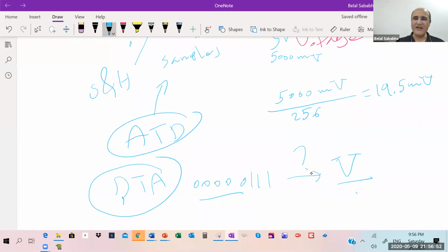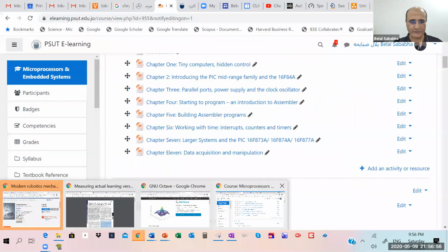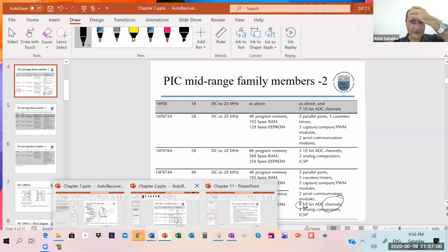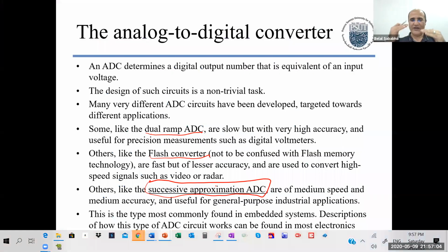So that's easy. Now, part of the successive approximation: the voltages I'm expecting are something between 0 and 5 volts, right? So you go to the middle, 2.5 volts, and you convert it into a number. Well, you give it a number, 128.